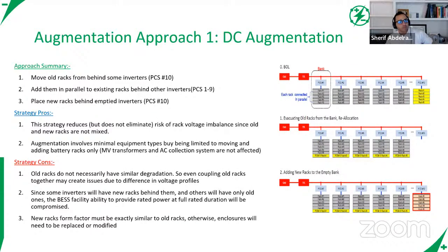But the way to mitigate some of that risk too is really through having a solid energy management system, and one that is monitoring these. At Flexgen, we're collecting 15,000 data points per second on our systems, and it's taking that data, seeing what's really happening at the cell level, and then responding and sending the right commands to these cells and modules to deal with these imbalances and differences really at the cell level.